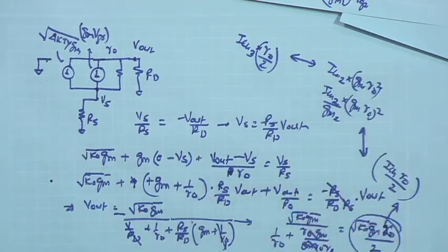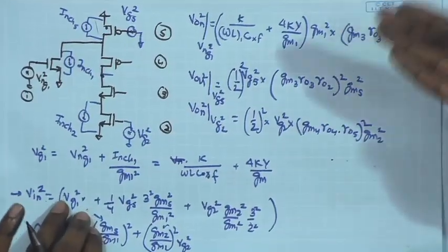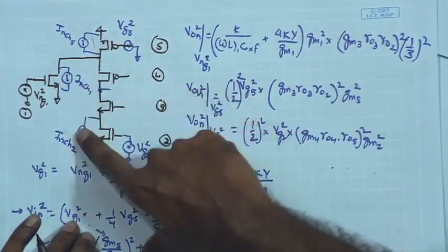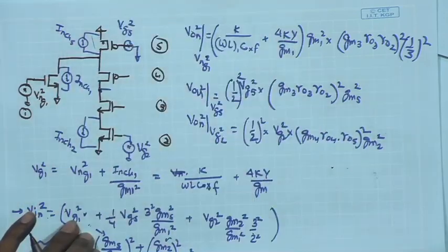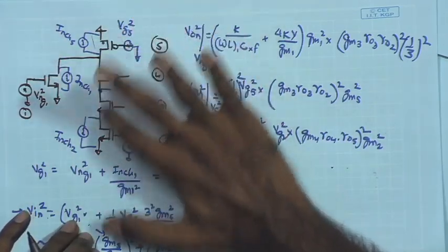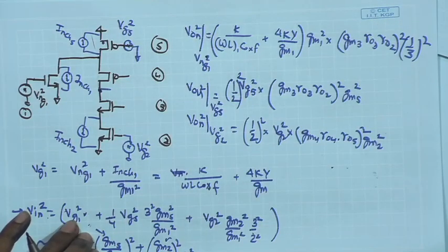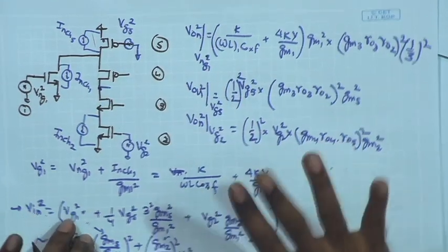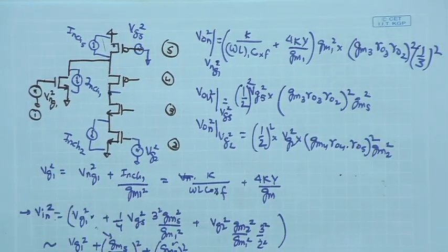Therefore, as compared to the noise contribution of the, I can call them common source devices, because their sources are grounded and their noises are contributed in the form of a common source amplification. As compared to those devices, the Cascode devices noise are lower by 1 upon Gm Rho factor, and therefore I can ignore them. So this is the analysis just to conclude this result.